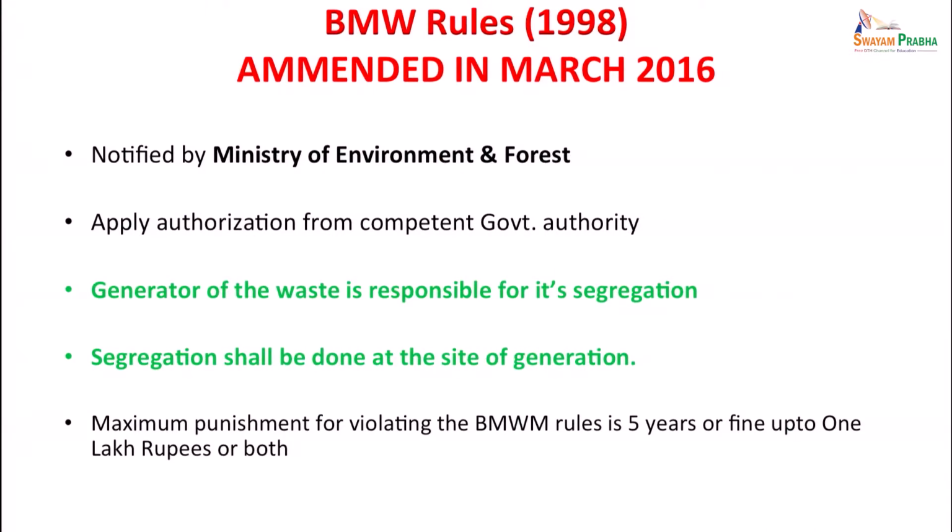Now, as far as the 2016 amendment is concerned, it has been notified by Ministry of Environment and Forest, and one has to apply authorization from competent government authority, whoever is disposing of waste. Generator of the waste is responsible for its segregation. Segregation has to be done at the site of generation, and there can be punishment if one is violating these rules up till 5 years or fine up to 1 lakh or both.